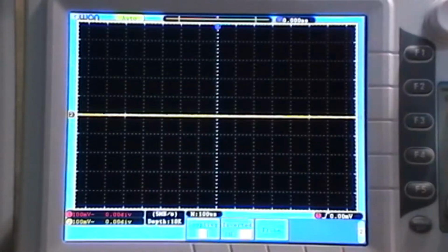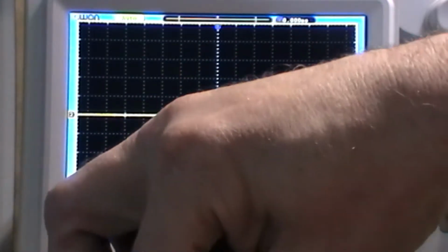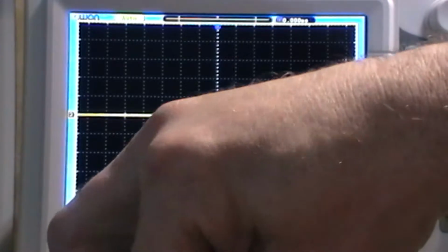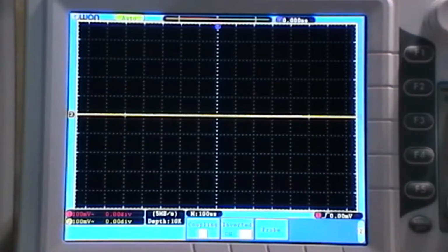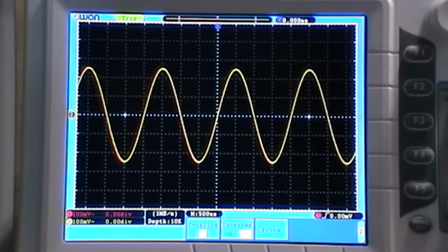Right, whip that one out. It's the 47 out, and we've got a 15 nanofarad in there now. So now I've got 15 nanofarad. Turn that on, and this time, because we've got an even smaller capacitor, we've got an even higher frequency at which it will